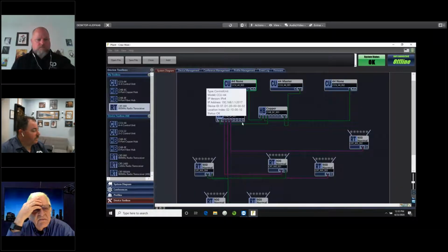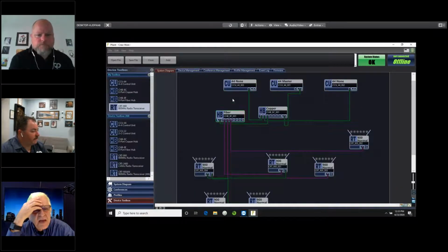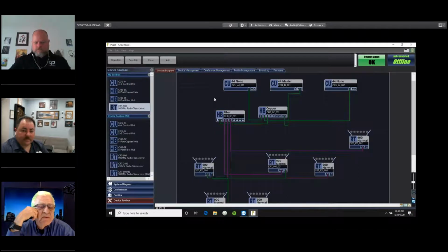Yeah, that's another advantage of adding control units: you add more inputs and outputs to the system. You can do it up to 4, which allows you to get 16 channels of 2-wire, 16 channels of 4-wire. This has come into play a lot for Kevin and I in scenarios where we're doing REMIs, and they don't want to use any 2-wire in the system because of feedback to whatever control room they're talking to across the country. So it allows us to add in more 4-wire capability and expand the system.